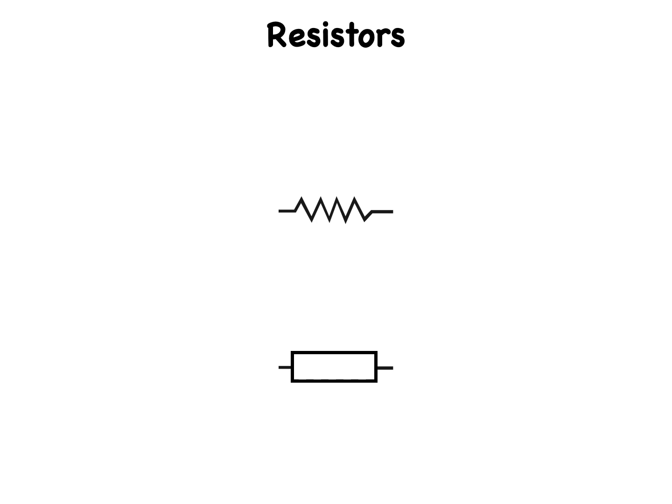The schematic symbol for a variable resistor with two leads looks like this. There are still only two leads. Other types of variable resistors exist, and they have three leads, two end leads and a tap. This shows two examples of schematic symbols for a three-terminal variable resistor, known as a potentiometer or a rheostat depending on the method of construction. Notice that both examples use the standard resistor configuration, and indicate that it's a variable type by means of an arrow symbol pointing to the zigzag part.